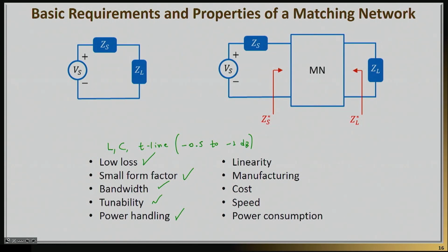Linearity is a huge issue as well. We have talked about linearity in the beginning of the course, but if I'm sending a single tone here, I really insist on a single tone towards the load, not multiple frequencies hitting my load. Of course, somebody has to be able to manufacture this at a reasonable cost. And speed and power consumption also come into the picture.